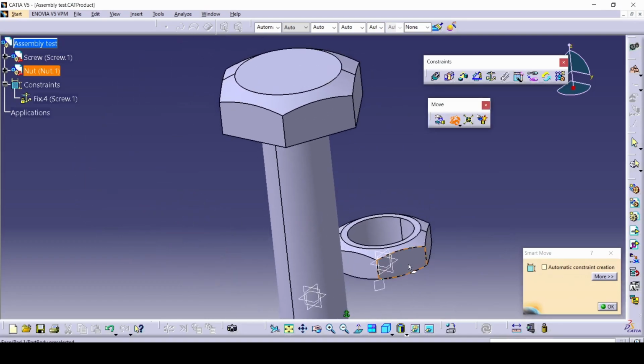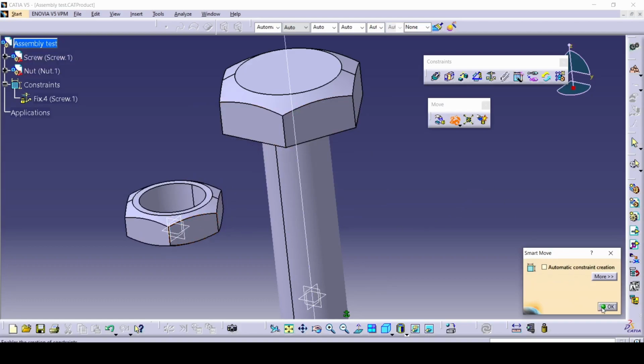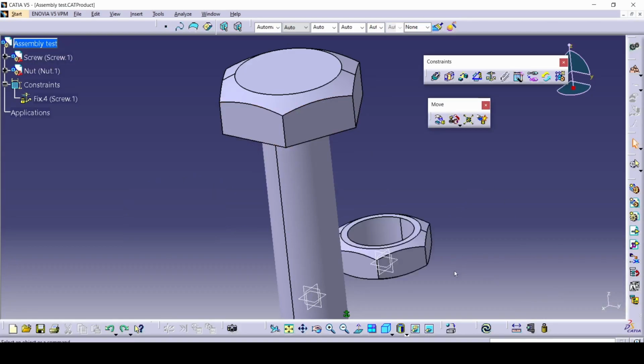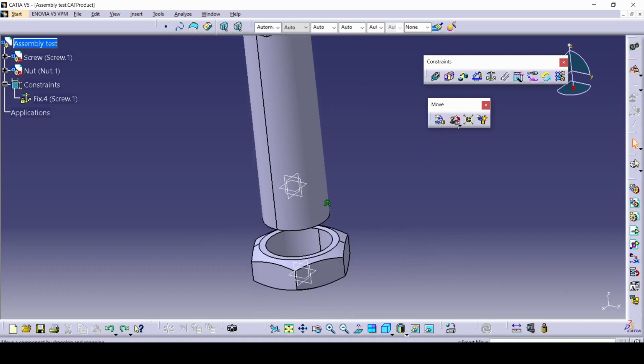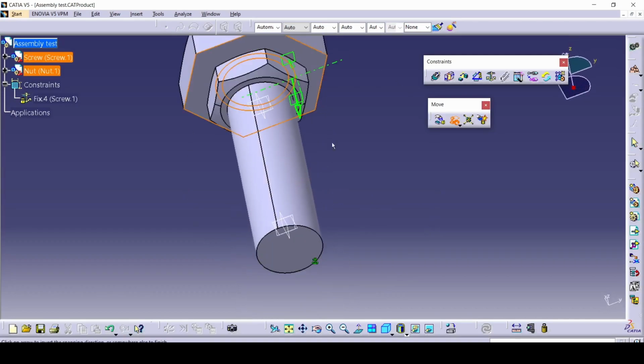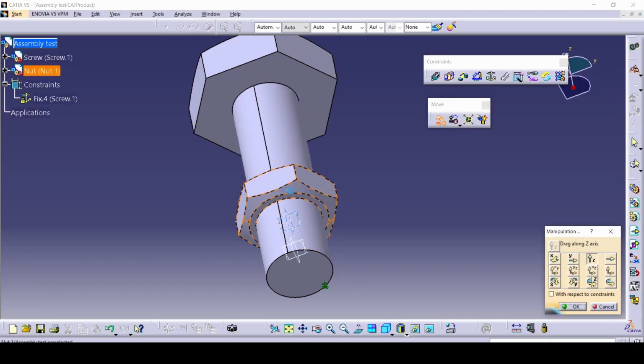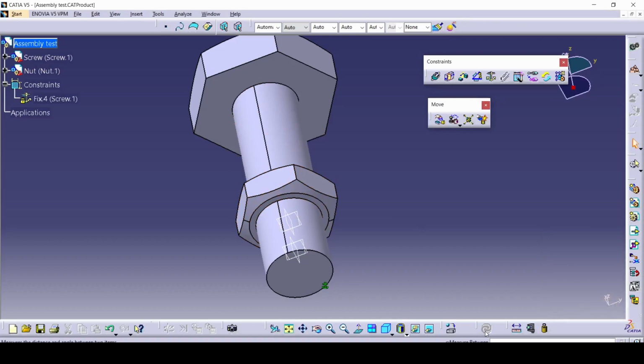And it's also snap mode, which is just snapping things together. I don't really like to use that. Let me just say Control Z, get it back. I like using snap because I can select this plane and this face and it's snapped right together. The only problem with this is that we do not get a constraint from that. So if I go into move again and I move this back down, I don't get an update bar.